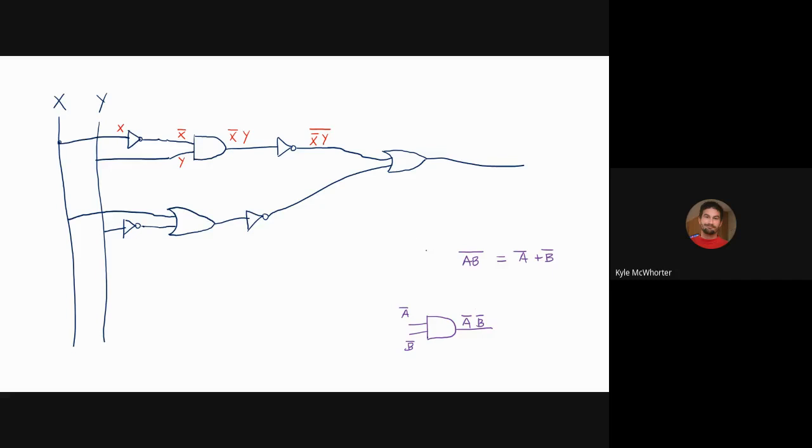If you had A and B going into an AND gate, then you would have A and B coming out. Then if you went through the inverter, you would have not A and B. So that is different from not A and not B. Does that make sense? I hope it does. I'll leave this here for a minute and then I'll erase it when I need the room.